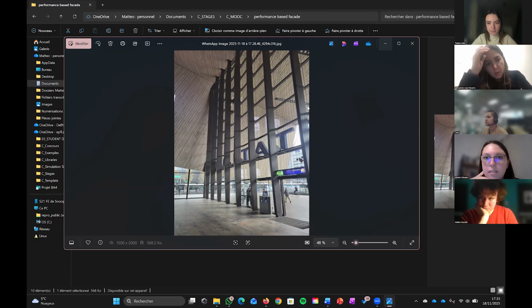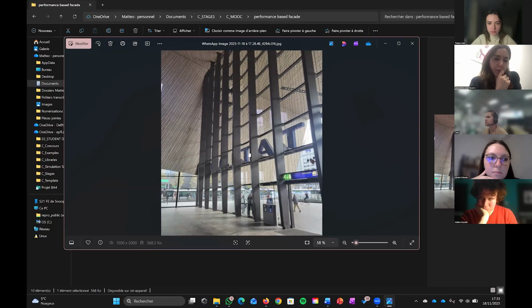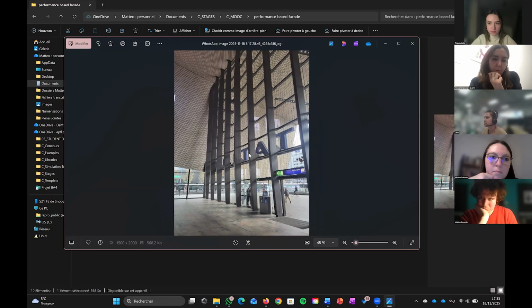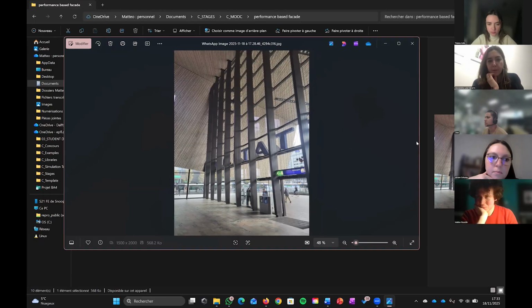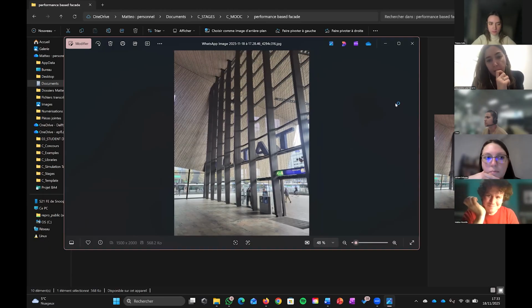Alessandra, what would you say? I agree, but I have a question that we can't answer with this picture: whether these mullions are also primary structure. It's difficult to see effectively. It could be, but it seems to me that there is a clear hierarchy between the horizontal, thinner transoms and the vertical mullions that are definitely supporting these horizontal transoms.